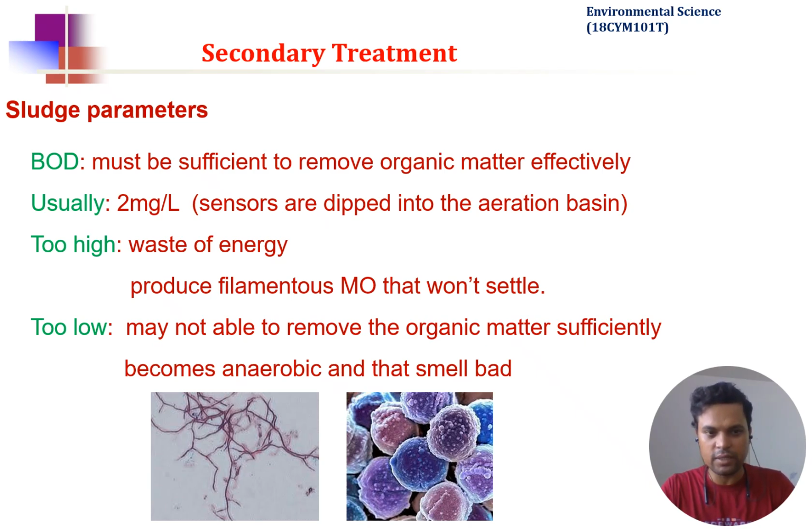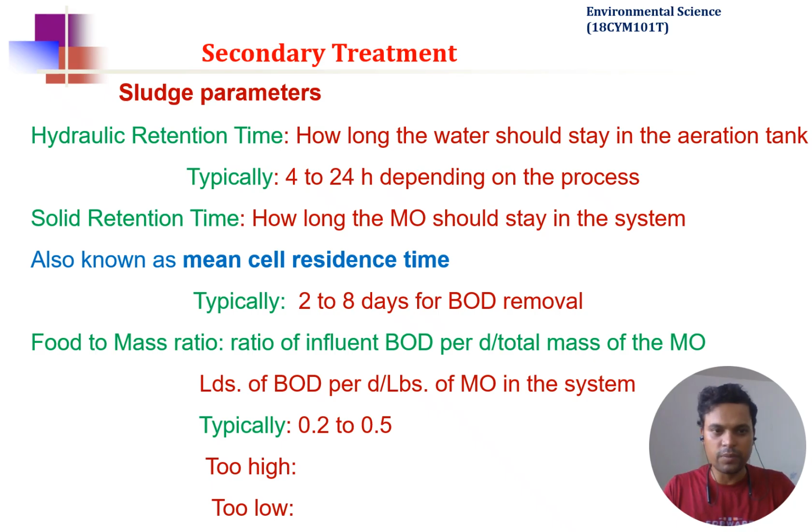Okay, so these are the few things that you have to remember. Then hydraulic retention time, that I was telling you earlier, is how long the water should stay in the aeration tank. Generally it is 4 to 24 hours, depending on the process. You can extend it a bit longer, but within 24 hours they generally discharge the water from the aeration tank, and they can recycle if it is required.